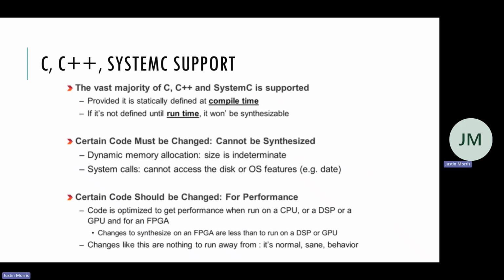So going along those lines, certain code must be changed. Dynamic memory allocation, you can't do this. No malloc, no dealloc, right? No dynamic memory size. You need to say that this array is going to be 10-dimensional. And that just goes back to no pointers.